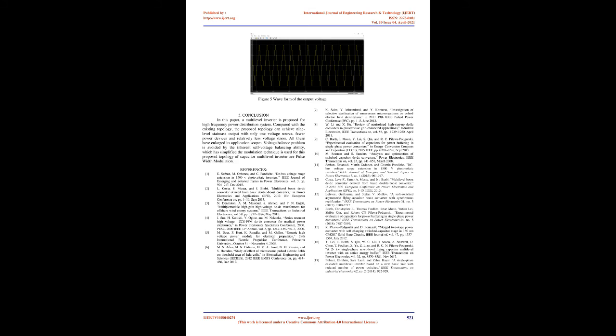MATLAB simulation is conducted to verify the performance of the proposed 9-level inverter, and the detailed simulation process is shown below. The output frequency is set to 1 kHz. The simulation waveforms of different output voltages are shown in Figure 3, the waveforms for different load currents are shown in Figure 4 when supplying different types of loads. Figure 5 shows the waveform of output voltage.